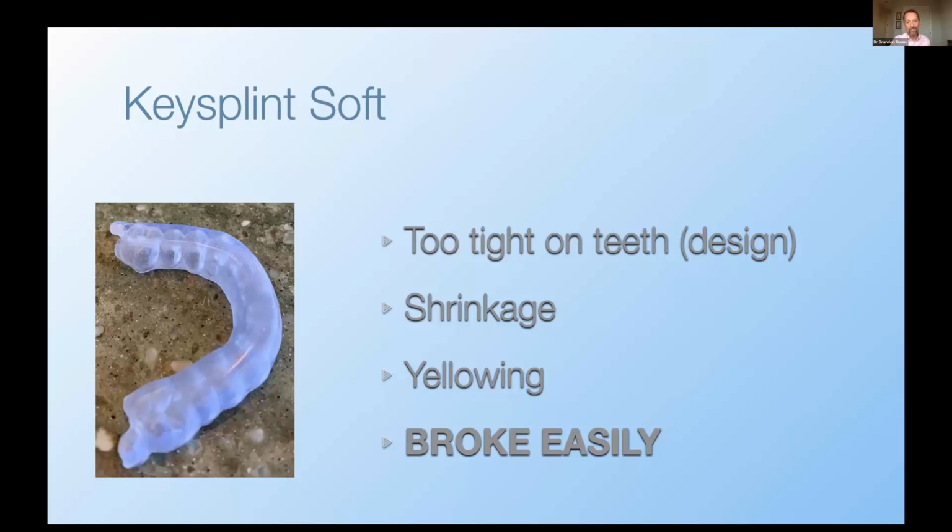We didn't have the shrinkage issue anymore. We didn't have the yellowing issue. If anything, we had this light blue color that gets a little bit clearer as it fades, and I really liked having that little bit of blue pigment. It is also great because if you're printing on a 405 nanometer projector, or a different type of printer, the polymerization is more consistent on a 385 or a 405.